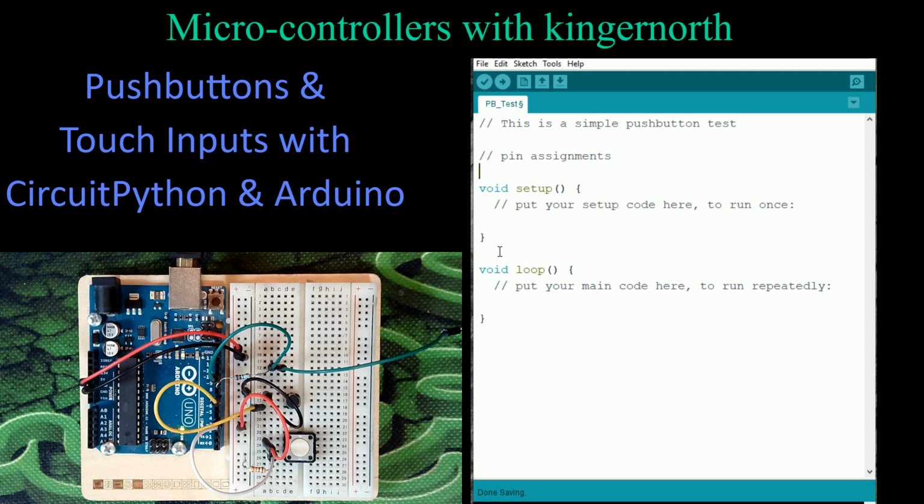And in this particular case, I have push button 1. I have it connected to actually input 4 is what's on that board. So way over here, this is actually input 4 that I've got the white wire here connected to. So that's what I'm going to do here. I'm just going to create that pin. So input, and this is going to be PB1 equals 4. So that just tells me that I've connected that to pin 4.